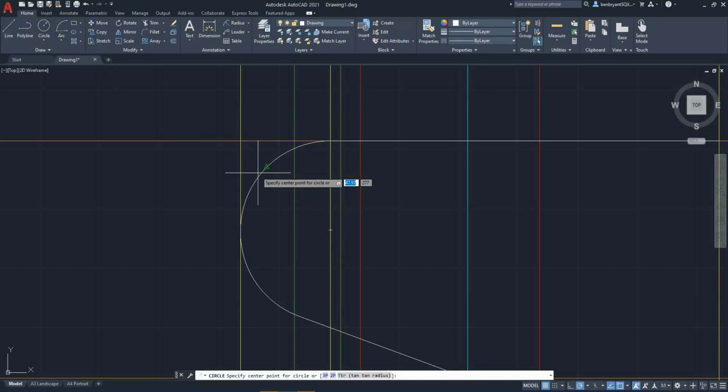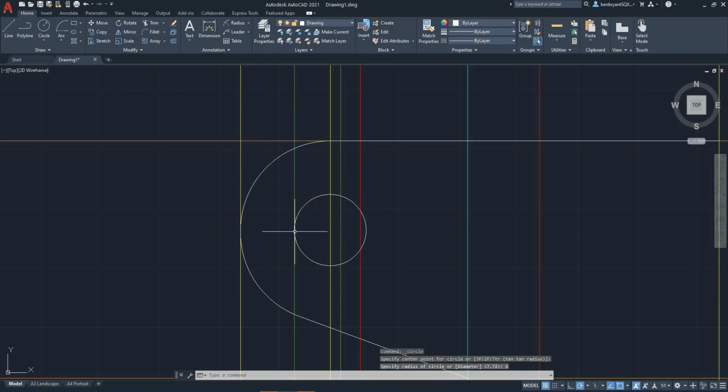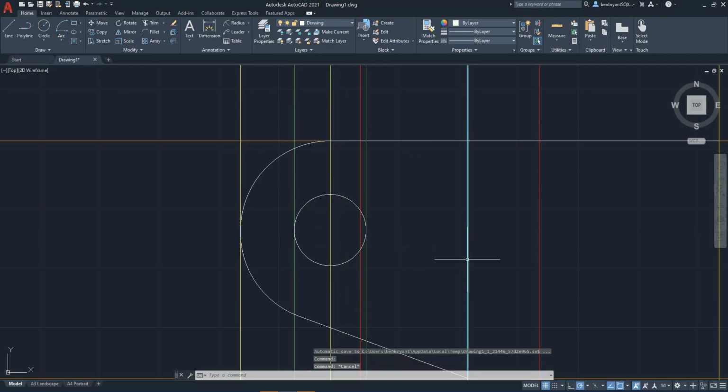We know that the center points are exactly the same as our arc, so I'm going to hover to get the center point pick up, and I'll put R6 in, which touches my 9 line. Now what I'm going to do is I need to move this X line. So I'm going to do a move. I'm going to put it on the edge of my circle, so I know that that is the full designated width.